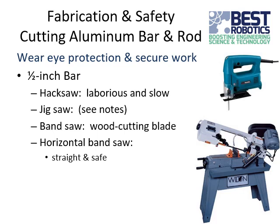You can use a jigsaw too. They use a metal cutting blade for that as well. Bandsaw, you can get away with a wood cutting blade on that, or if you have a metal cutting one, that works too. Or a horizontal bandsaw if you actually have one of those. These are all options you could use. But like I said, I like the hacksaw personally.